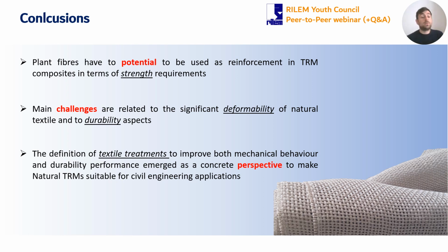What we have seen with this presentation is that plant fibers have the potential to be used as reinforcement in TRM composites due to their strength capacity, but of course the right amount of textile within the mortar should be assessed to have the best performance. We have seen the main challenges related mainly to the significant deformability of natural textile and to durability aspects.